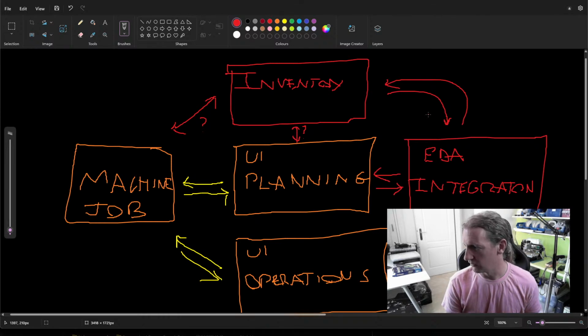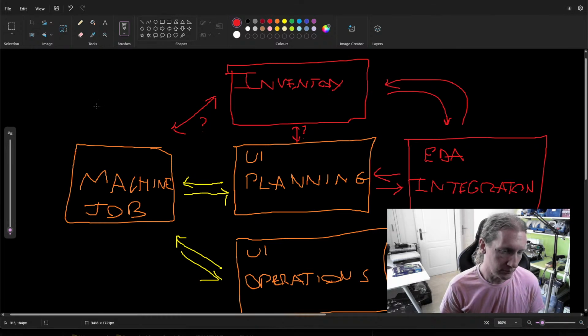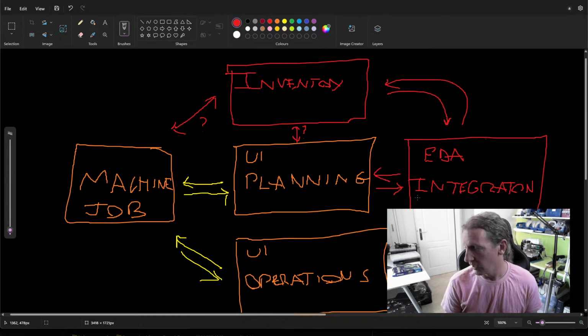It's quite common to realize that you've got typos in your schematic, or you've got the value wrong because you copied and pasted a capacitor into the wrong place, and now you've got to update your board files. But you're never changing the Gerbers at this point. You're literally just changing the logical representation of the components in your schematic. So this needs to be very repeatable. It also needs to be very quick and not intensive.